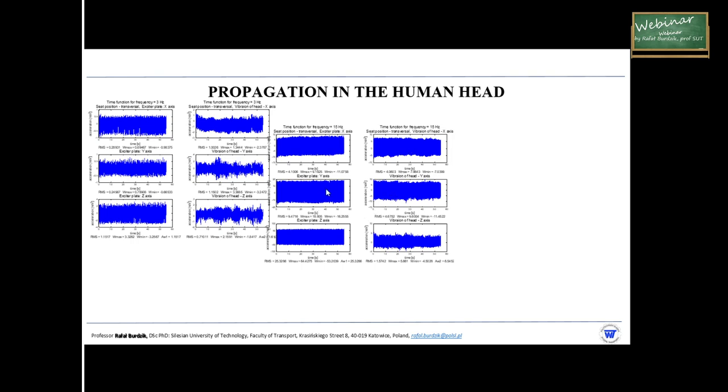so it is hard to find the differences. But if we consider the y-axis and z-axis, you can see that it is twice less here on the head than on the excitation plate. But on the z-axis, which is the vertical vibrations, we've got 10 times less, because it is 15 on the excitation plate and just 5 in the head position.